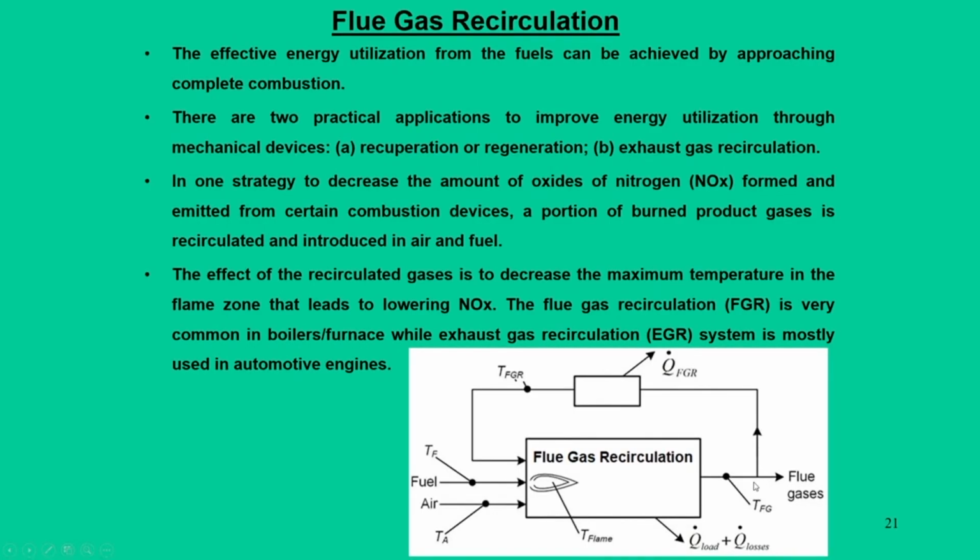But in another scenario, when you have a rich mixture, that means we have not extracted the fuel energy completely. So the mixture still has some capability to initiate reactions. Under those conditions, we use the concept called recirculation, which we call fuel flue gas recirculation. Recirculation means that some part of the exhaust product, before it is fed out, is again fed into this system or the reactor.